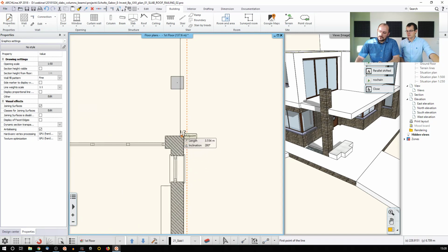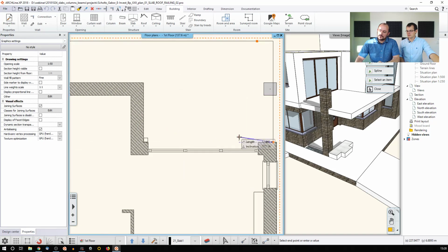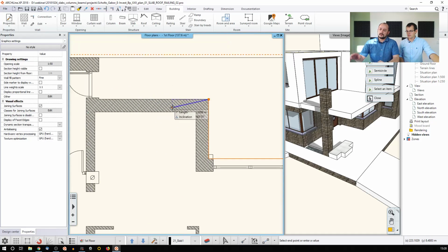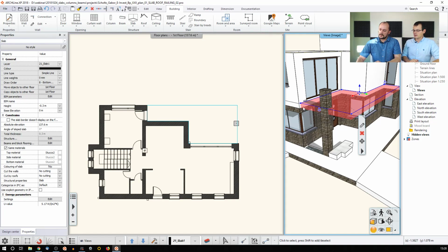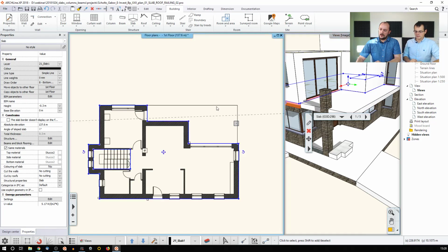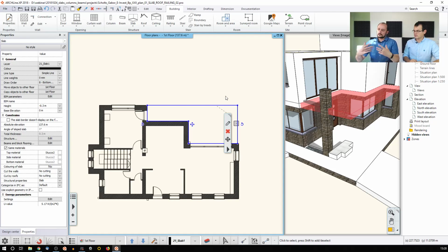And the way it works, you actually need to set up the first point and then the second point. And actually, you can create a kind of polyline cut following the external contours of this building. And then when you say, OK, enter, the software breaks this into one and another item. And now I can start detailing this slab and adding layers and beams and other things like that. Perfect. And that was actually the beginning of the work with slabs.